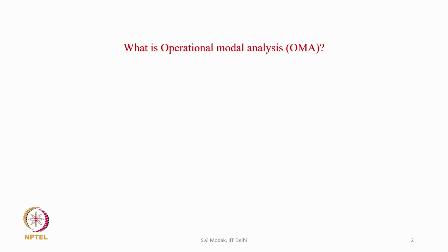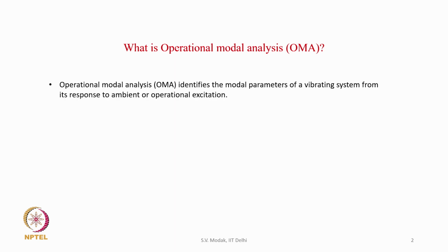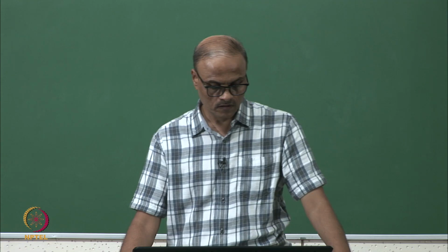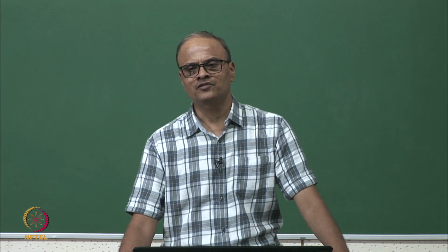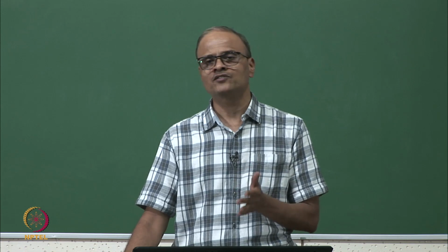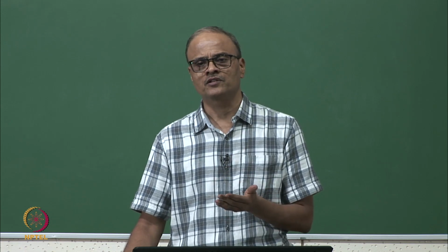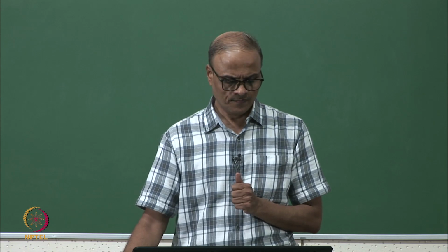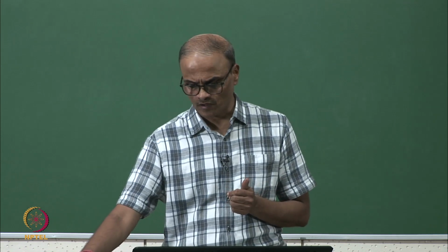So, what is operational modal analysis? Operational modal analysis identifies the model parameters of a vibrating system from its response to ambient or operational excitation. It is seen that some structures in practice are subjected to random ambient excitation during the service, and operational modal analysis relies on measurement of the resulting responses to find the model parameters. So, this is different from experimental modal analysis.